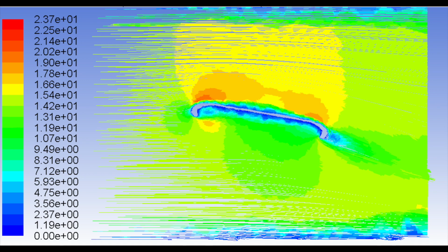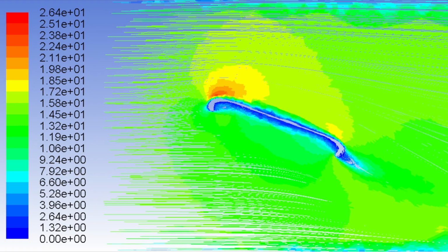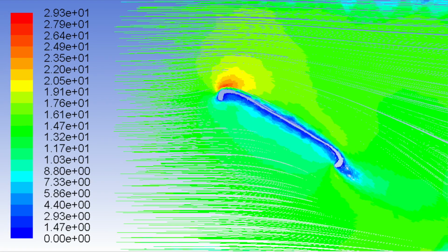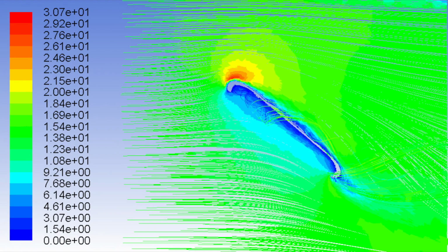It also analyzes how the disc interacts with the surrounding air when released into the wind at 15 meters per second. This data is used to determine how the frisbee will react when different angles of release are used. From the diagram, we can see that as the angle of attack gets steeper, drag is created from the increasingly large surface area facing the inlet of the simulation.